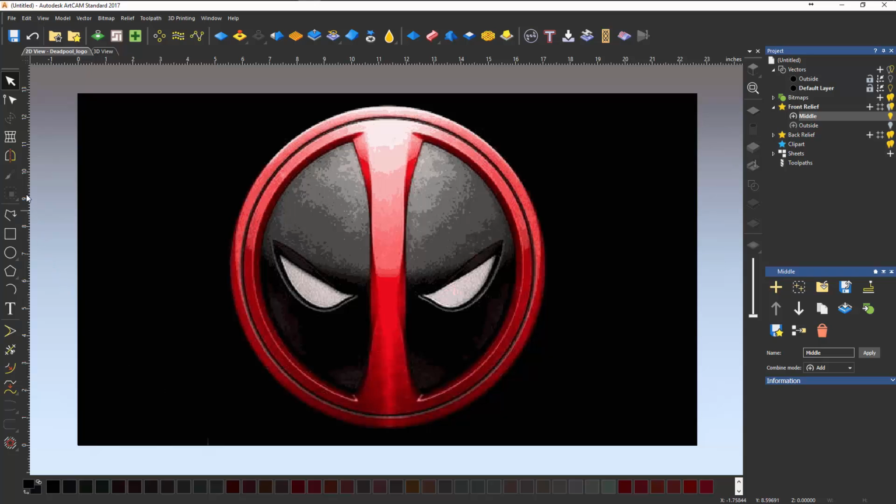Okay, so over on the left side, we have in our ruler a hidden grid line. So if I left mouse click and drag this out, I have a snappable grid line that I'm going to set up in the center of my model. Now this can work one of two ways. I can drag it out and eyeball exactly where I think it needs to be. Or once I drag it out, I can right click on it and go to Edit Grid Lines and set an absolute value.